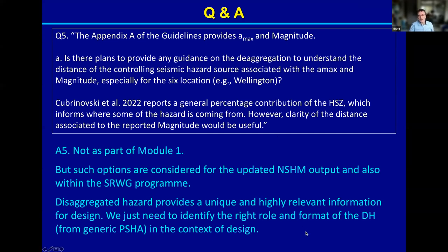I would also point out that in my view, disaggregated hazard provides unique and highly relevant information for design. We definitely want to use it. We just need to find the right role and format for the disaggregated hazard when using generic probabilistic seismic hazard analysis in the context of design. And this is what this Seismic Risk Working Group program is trying to address.